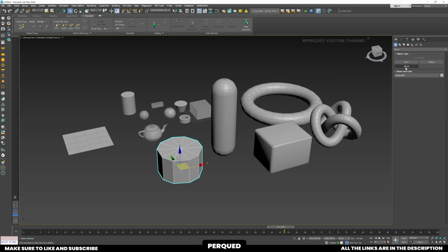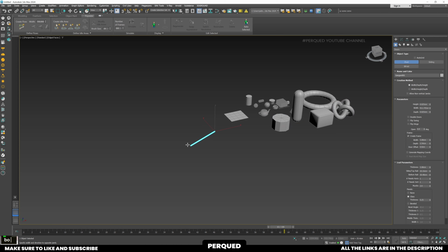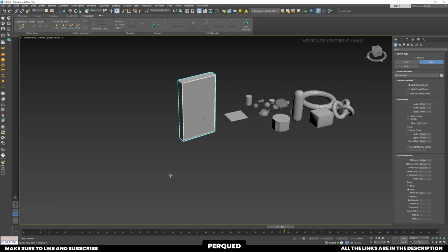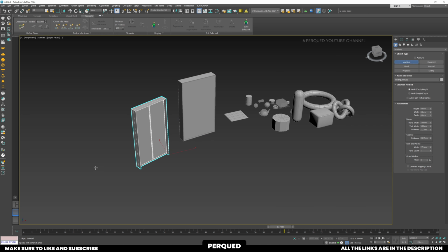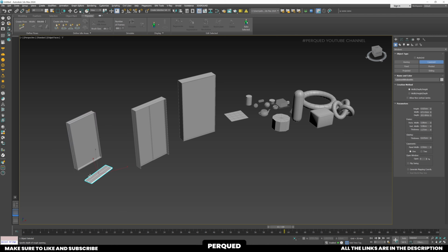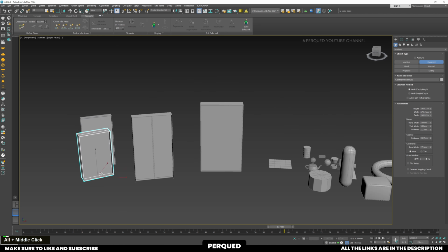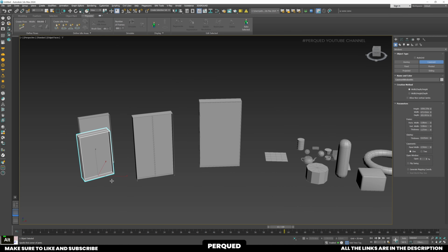We have the doors and windows tab, where you can make doors and windows. I personally never use these because it's kind of buggy, to be honest. To create these, just follow the instructions from the bottom left corner. These doors and windows have some good parameters like opening and closing and adding panels and stuff. If Autodesk fixes the bugs in these doors and windows, these can become the best door and window panels in the market.